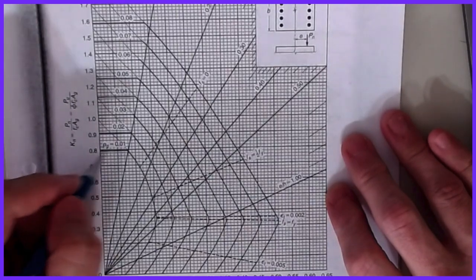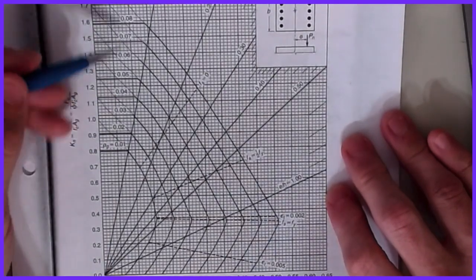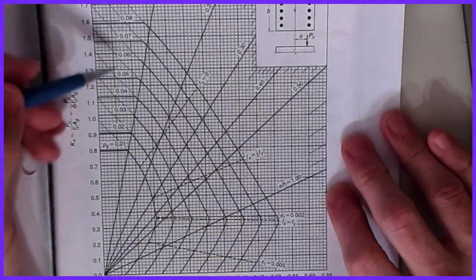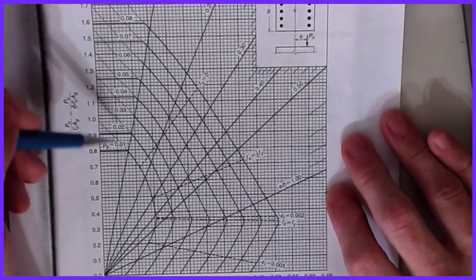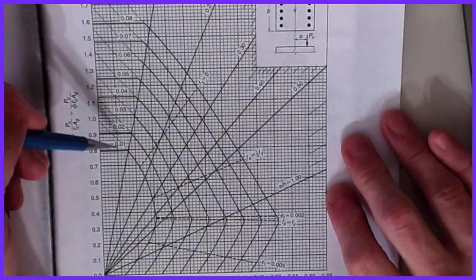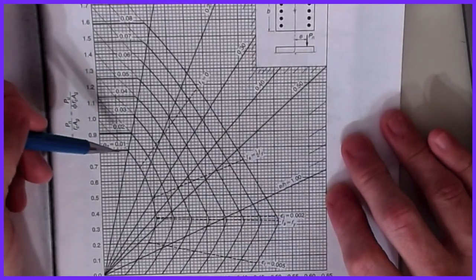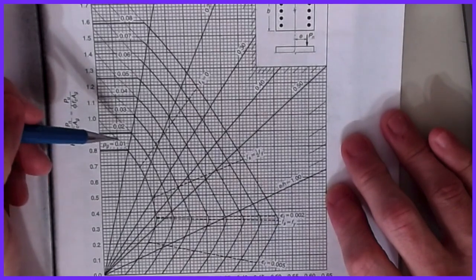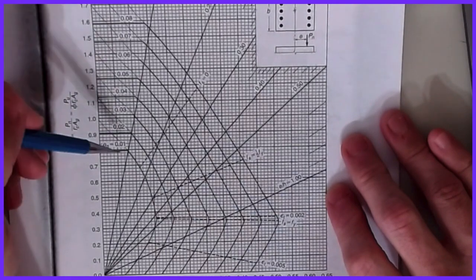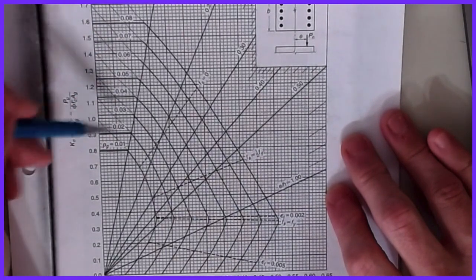The lowest line on here is 1%, that's rho g of 0.01. And the maximum that you'll see up here at the top is 0.08, and every line in between is represented. This is because these are the ACI limits for reinforcement in a column. Remember, we talked about those back in one of the earlier column videos about the min and max steel that can be put into a column. This will ensure a behavior that we're expecting, whether it's ductile or preventing a compressive failure, all those kinds of things. So those are our curves here.